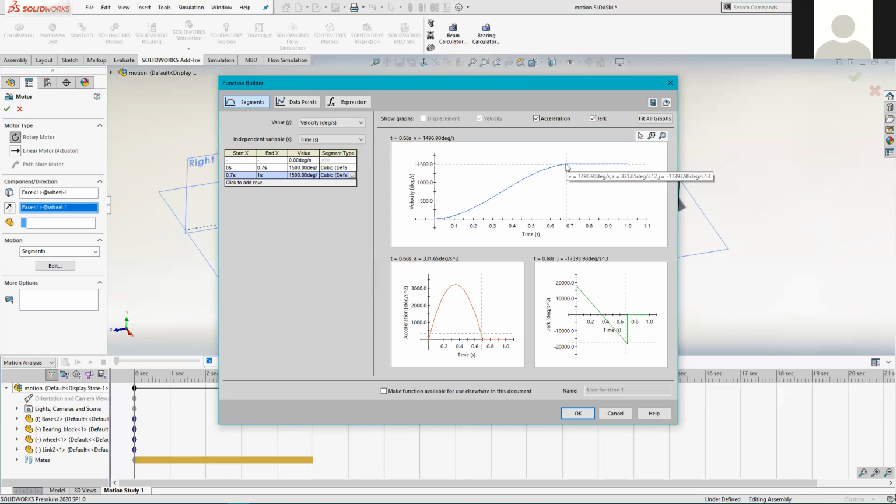The reason for that is, having run these simulations a few times, you have to give it a certain period of time to almost stabilize so that you can see regular peaks and troughs on the stress values that we're getting. There is a tendency, if it's too near in terms of time to the point at which it was accelerating or decelerating up, that corrupts the results slightly. So you have to run it at a constant rotational speed for at least a period of time. And the periods of time that we're talking about are quite small.